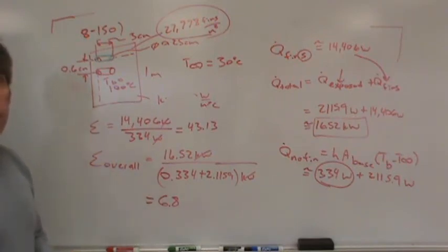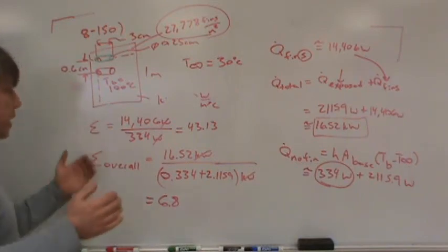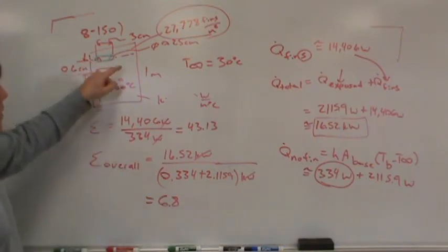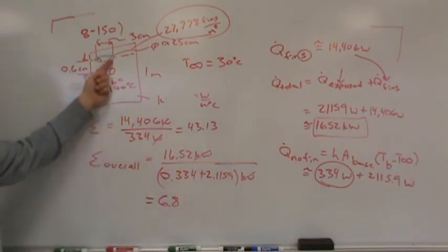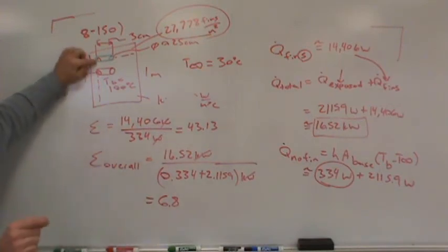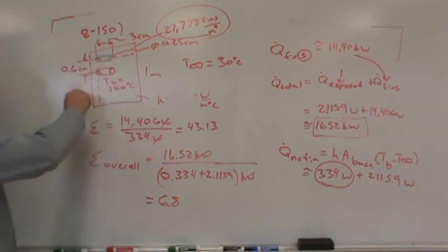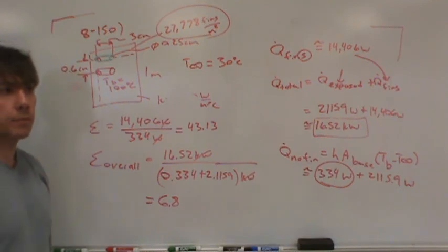Right. What you're saying is, it doesn't seem fair because this area would have been there anyway. And that comes into the effectiveness. That question is answered by the effectiveness. Now, another way of looking at this, the fin does not necessarily have to look like this. It doesn't have to be a round cross-section. It could actually taper down. So we could actually lose that area, you see? So technically that area is lost no matter how we look at it. It becomes fin area. And not only that, but remember, a fin is not 100% efficient. So the temperature out here is actually less than it would have been had it been on the base. That's another reason for not including it. Good question. Anything else? All right.